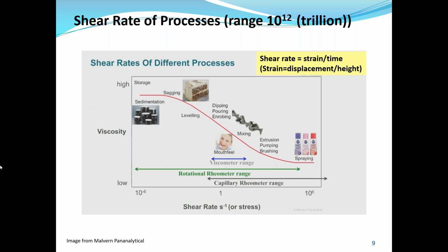Sometimes they do. And a lot of times, if you want to do that, you just need to tweak the parameters of either the viscometer or the rheometer to see if they can match. And that could be the plate type, the plate speeds, the force, the height of the sample, and so on. So, with some work, you might be able to get some good correlation with that, but it really depends on the sample and being very careful about your experimental considerations.